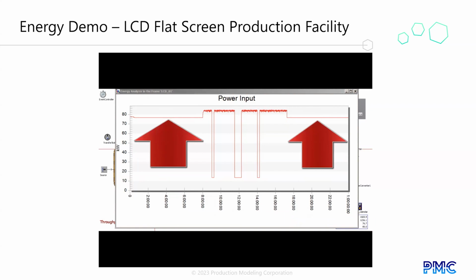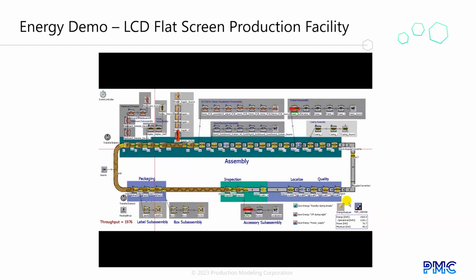After looking at this chart, you may have guessed that we could save even more energy by switching to the off state during off shift or unplanned time, instead of leaving everything in the operational state. Since these periods are long, we are switching to off state instead of standby for even more energy savings. To do that in our model, all you have to do is check the on-screen Save Energy Off During Night